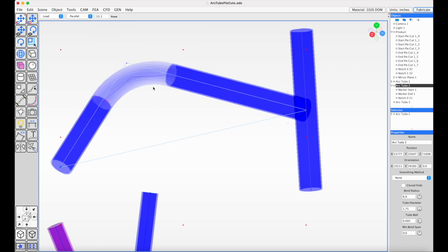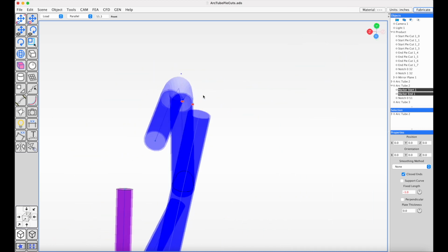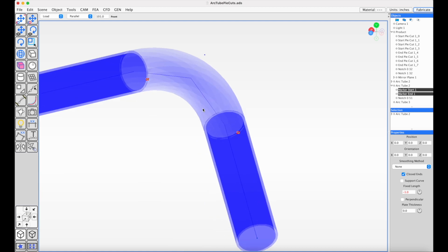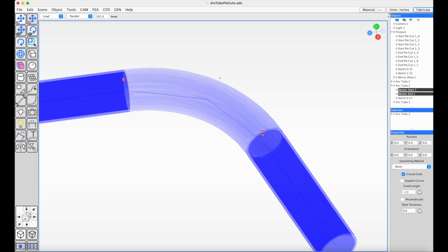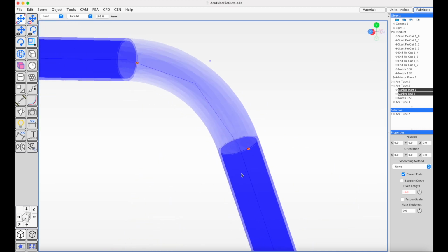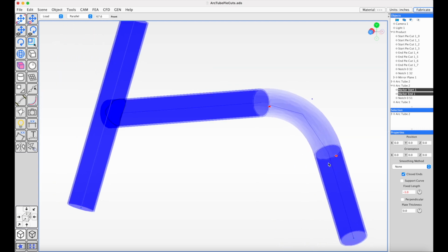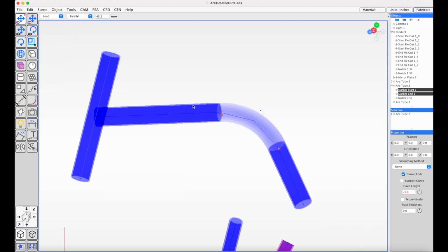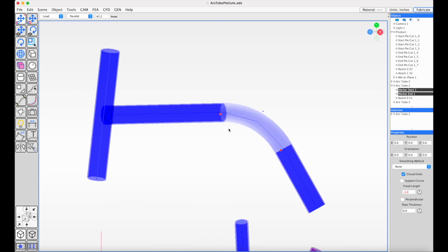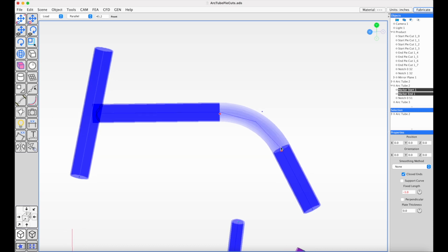So if I click on this, it's going to add bend marker, and you can see they're just a little pinhole scoring the notcher will make on the tube, and these allow you to align, position the tube in the CNC tube bender or manual tube bender so that you know that the tube is loaded in the correct orientation and the correct location along the tube so that the part that you bend is correct. And these geometry take into account bend radius, radial growth.